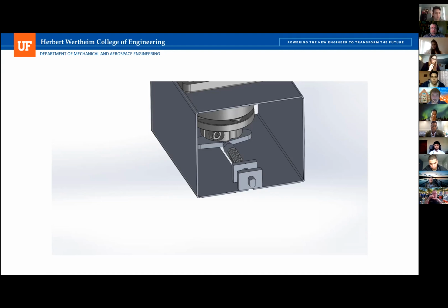So as it turns and the rod's trying to go up that surface, you can imagine there's a lot of side load there, and it can stick as it tries to work its way along that surface. So it's just thinking about, would you need a small ball bearing or a wheel on the end of the rod, which helps it move more smoothly?